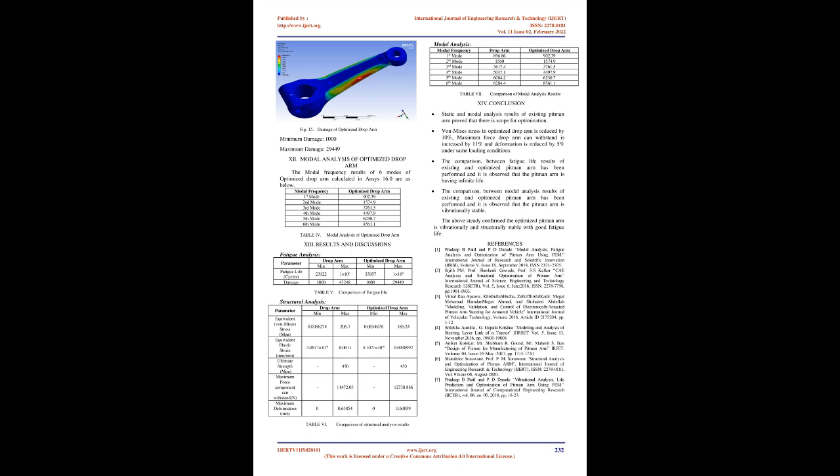The comparison between modal analysis results of existing and optimized pitman arm has been performed and it is observed that the pitman arm is vibrationally stable. The above study confirmed the optimized pitman arm is vibrationally and structurally stable with good fatigue life.